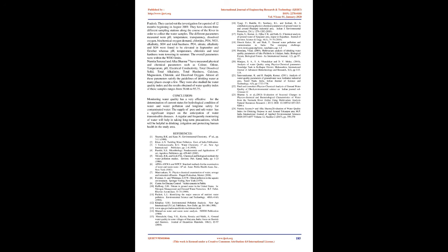Iron content above the permissible level of 0.3 ppm was found in 23 districts from 4 states, namely Bihar, Rajasthan, Tripura, and West Bengal, and coastal Orissa. High levels of arsenic above permissible levels of 50 parts per billion, ppb, was found in the alluvial plains of Ganges covering 6 districts of West Bengal. Presence of heavy metals in groundwater was found in 40 districts from 13 states, viz. Andhra Pradesh, Assam, Bihar, Haryana, Himachal Pradesh, Karnataka, Madhya Pradesh, Orissa, Punjab, Rajasthan, Tamil Nadu, Uttar Pradesh, West Bengal, and 5 blocks of Delhi.